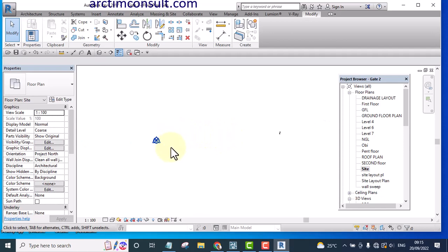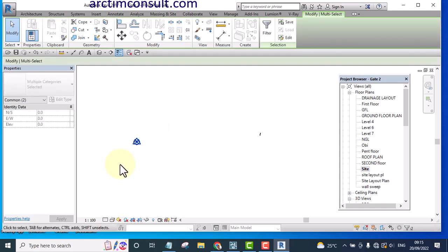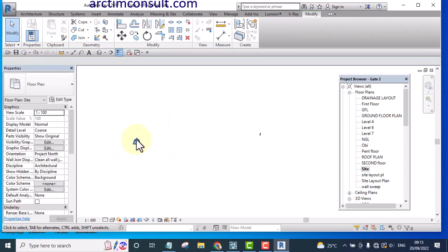And what I'm going to do now is I'm going to move this base point to where I want to have my pivot point. Because if I want to swing this gate now, it has to swing on its axis. So for me to be able to have control at where it is going to swing, where it is going to rotate on its axis, I need to move this survey point to that point, because this survey point is what is going to determine its pivot point in Lumion.